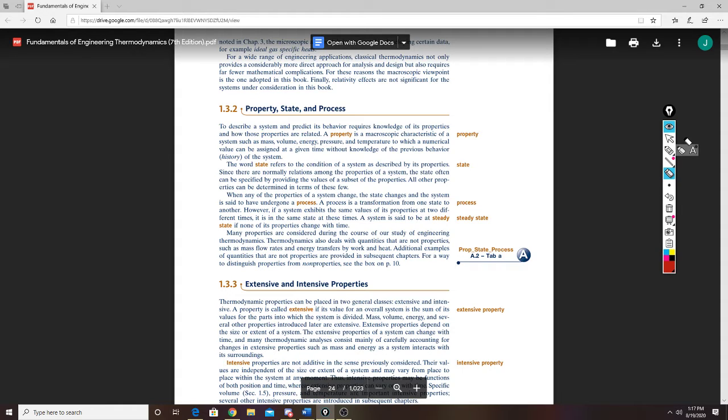And the more important definition for this is that in a power plant, they usually use steady state conditions to describe how much power is being made every hour or something. So for example, obviously mass flow rate is going to change based on what is coming in, right? But you can't possibly know the variance and all that. So steady state conditions essentially mean that when something comes through the system, we just treat it as steady. Like we have this one amount of mass coming in, this one amount of power leaving.